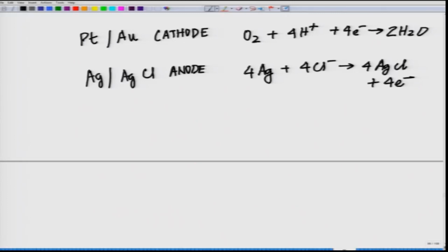Similar electrodes have been formulated for detection of NO, which is another biological component, hydrogen sulfide and carbon monoxide. So, what it is essentially doing is, we are measuring the current using the amperometric technique, by virtue of which one can figure out the concentration of oxygen which is dissolved in the analyte.